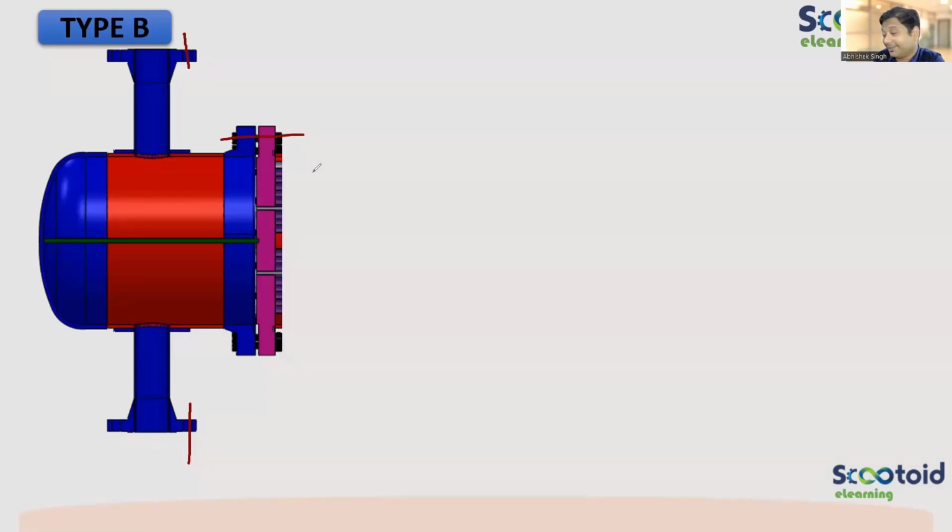Which one will be cheaper to fabricate? Type B, right? Because type A is having two flanges. Flanges are always costly. If it's a flat head, the thickness is very high. Remember that. Cylindrical parts have very little thickness for the same pressure, while for the flat head, the thickness requirement is very high because of the configuration. So first of all, thickness will be higher. There will be gasket and bolting introduced, which is not there in type B. So it's easy to fabricate, but difficult to clean.